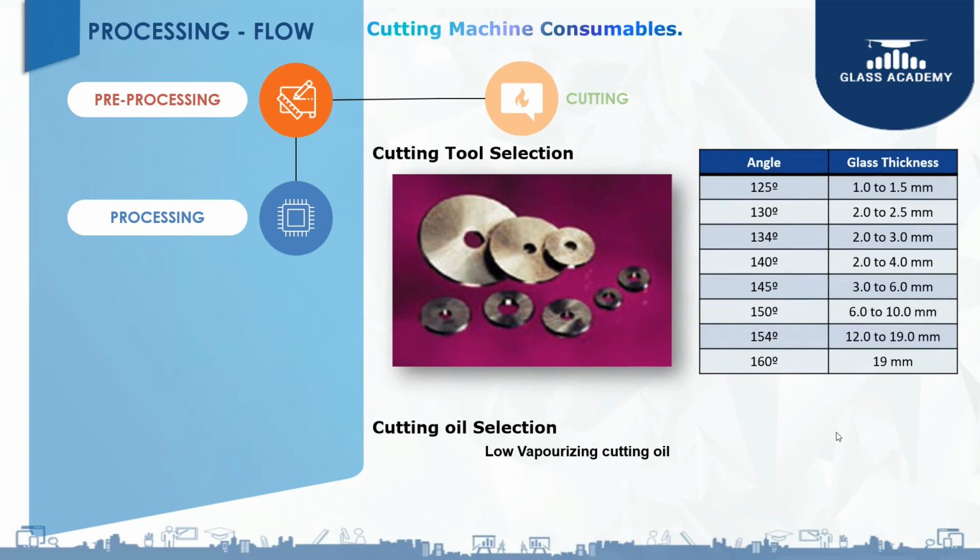So this is on the cutting wheel. We have spoken about the cutting, but what type of cutting wheel is used? A tungsten carbide cutting wheel will be used, and for every thickness, there is a specified angle. As you can see, this is the cutting wheel disc. This cutting wheel will be approximately 2 mm in diameter. It will be very minute, 2 to 3 mm.